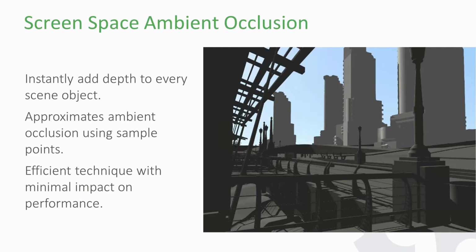So we want to have occlusion, which is the absence of light in various corners and hard to reach places across our scene, because obviously in real life there's shadows in every crevice, and it helps provide volume to the various models. But if we were to calculate the shadowing for all objects in the scene, it would be cost prohibitive in terms of computing power, and we wouldn't be able to do a real-time simulation. So what we do instead is sort of a cheat, which is a post-processing effect that we're applying to the entire screen, a technique coming from computer gaming, which is called screen space ambient occlusion. And what it does is that it samples the scene to find corners and edges between objects, and then it draws a shadow over it, and it blurs it, adds some noise, so that it looks like a shadow and not just a black line.